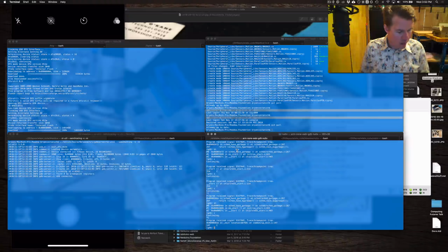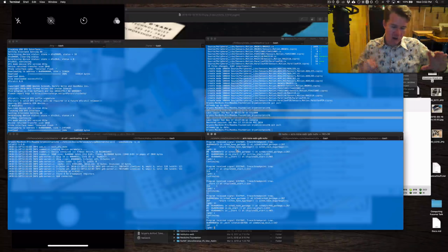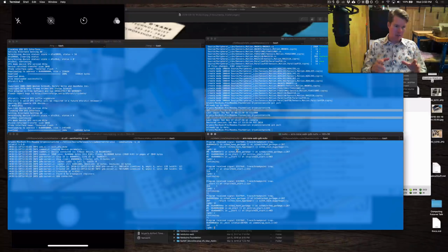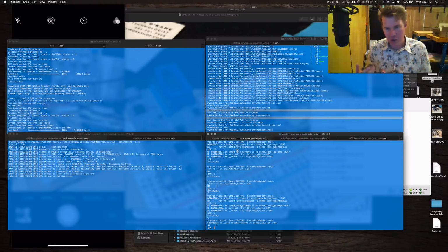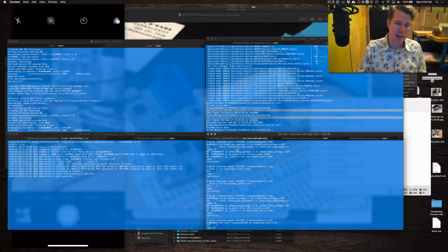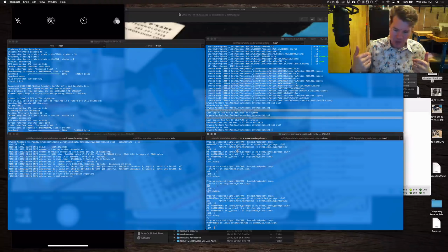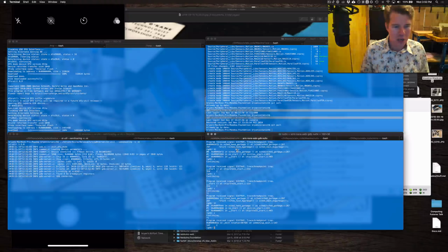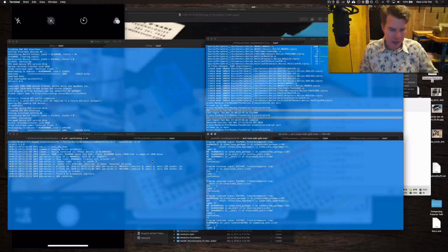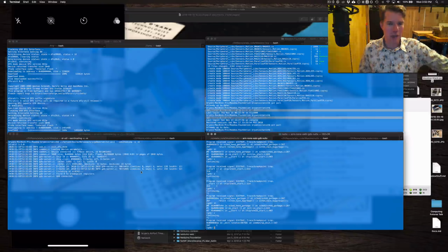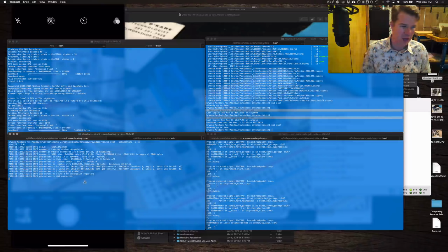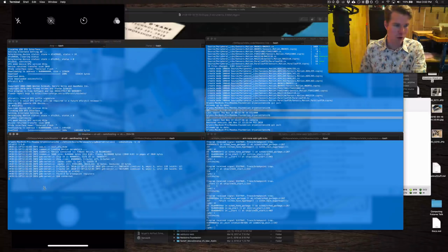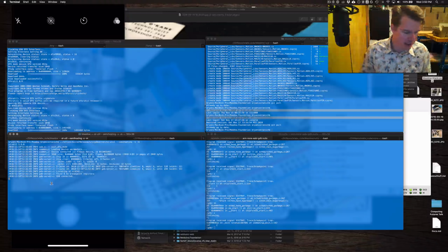Basically, what we've done is we've implemented this thing called semi-hosting. Semi-hosting allows you to connect a host computer to the device, and it exposes the host computer as if it were a peripheral. So we can do console.writeLine, and the console.writeLine comes over our semi-hosted ST-Link, and then we can see that. When we do hello world, we can actually see hello world output over this semi-hosting.